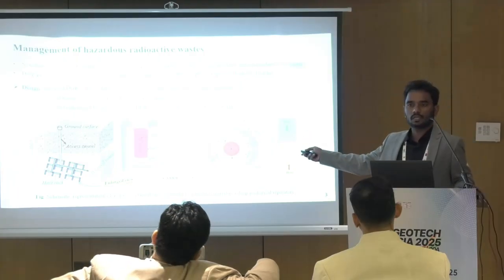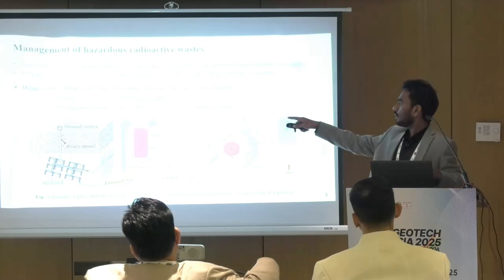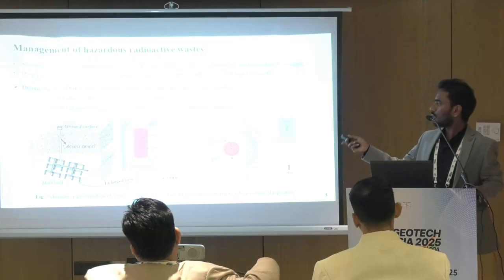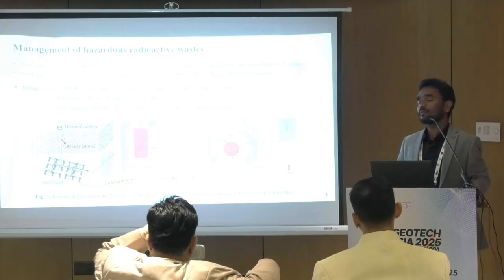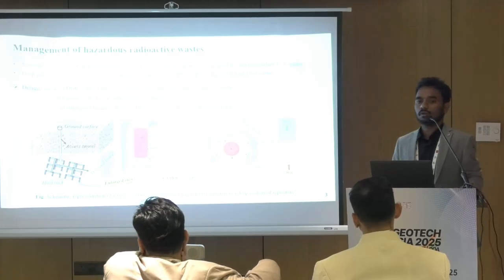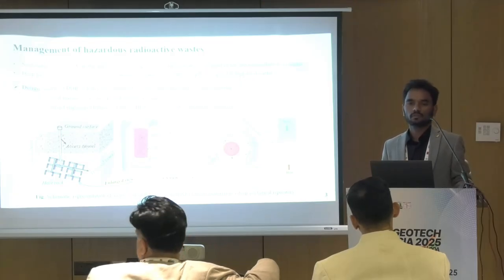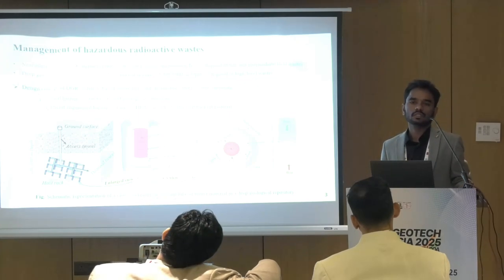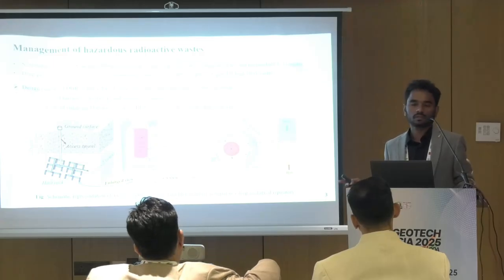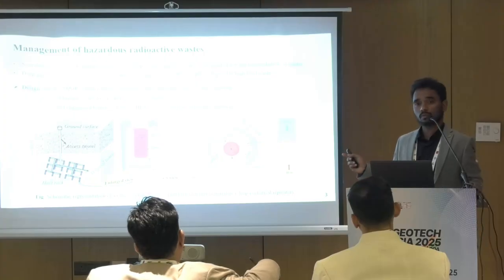At the center, this is radioactive matter, and the bentonite is compacted in layers. Next to this is rock. If you assume the real condition in the field, from one end water is coming, because when constructing those rooms there is a chance of faults or earthquake movements in the future. This is a permanent sealant, so it has to be sustained for more than thousands of years, because the activity of radioactive waste is a chain reaction, so it has to be stored more than thousands of years.